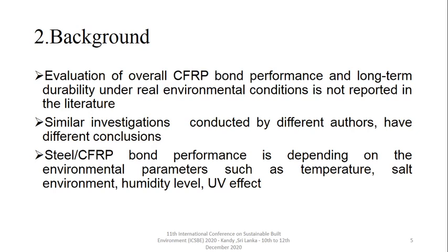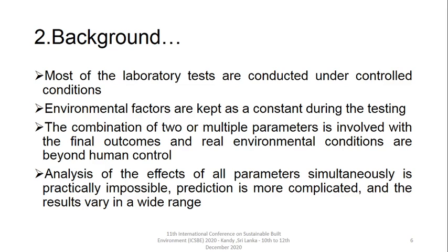Background. Evaluation of overall CFRP bond performance and long-term durability under real environmental conditions is not reported in the literature. Similar investigations conducted by different authors have different conclusions. Still, CFRP bond performance depends on environmental parameters such as temperature, salt environment, humidity level and UV effect. Most of the laboratory tests are conducted under controlled conditions. Environmental factors are kept constant during the testing.